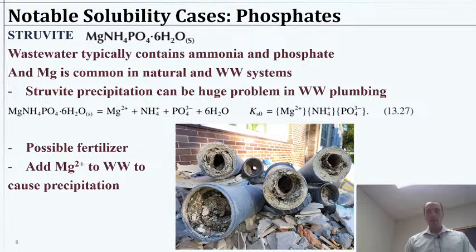So this was highlighted by one of the books, and I don't know if this is performed much in practice or what the typical challenges might be, but it really would solve quite a lot of the typical challenges, which would be the nutrient control. So tertiary treatment would often target biological processes that could do this, get rid of the excess ammonia, so nitrogen removal, and get rid of phosphate as much as possible.